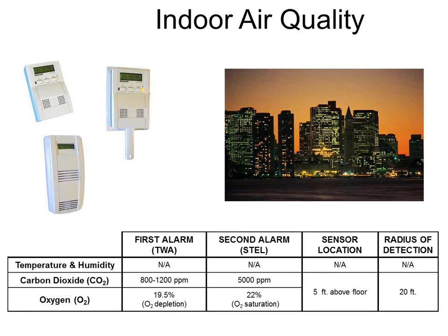Some standards, like the LEED standard, for example, prohibit you from putting them in the return duct. You have to put them on the wall. Putting them in the return duct ends up giving you an average diluted answer instead of giving you a factual answer.